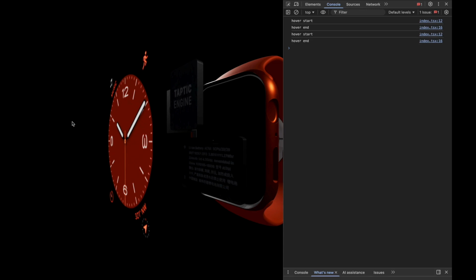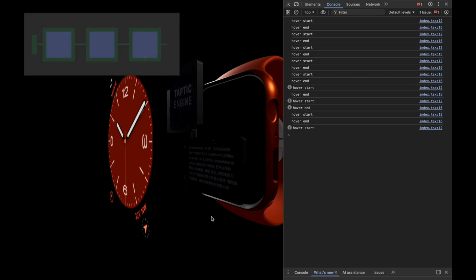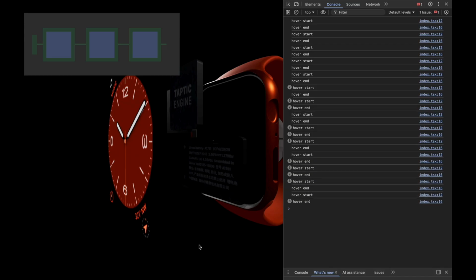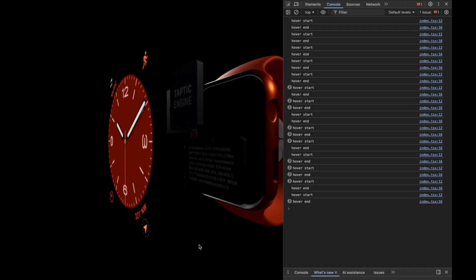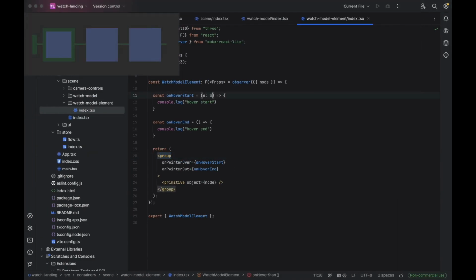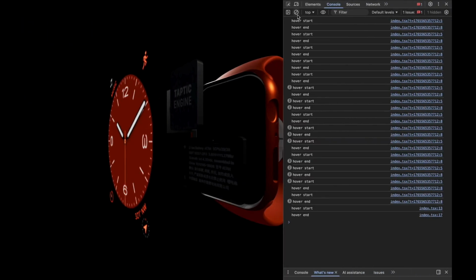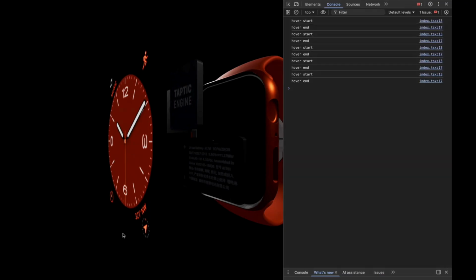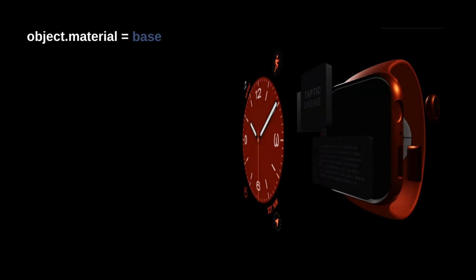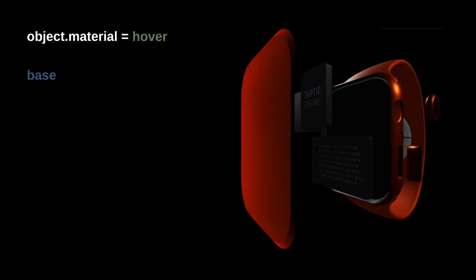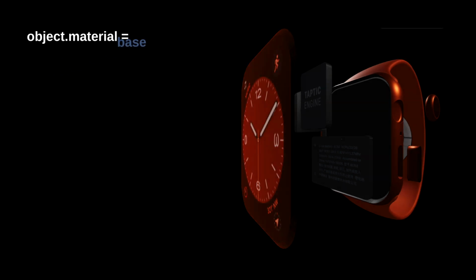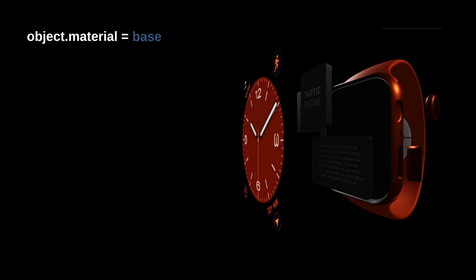There is one small nuance here. After hovering over an object, the ray used for object detection continues to propagate. This can result in multiple elements being registered at the same time. To prevent this, I manually exit the handler after the first object is registered. Next, on hover, I want to replace the material of the object with a different one. When the cursor leaves the object, the original materials should be restored.